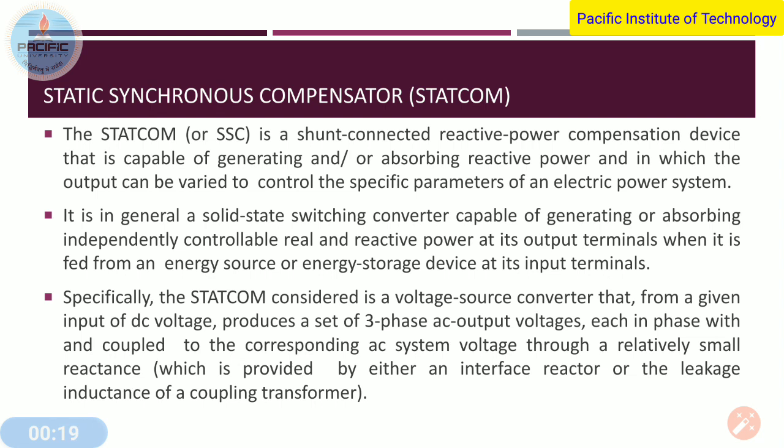Before this lecture, we already discussed the synchronous compensator. A synchronous compensator is nothing but a synchronous machine which is operating at no load. So a synchronous motor without any mechanical load can work as a synchronous compensator. The synchronous compensator is a synchronous machine which, when overexcited or underexcited, is able to produce or consume reactive power.